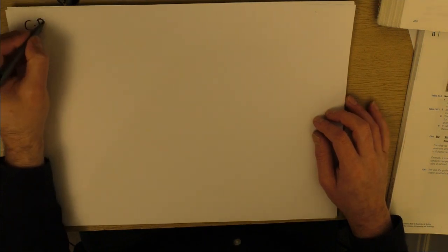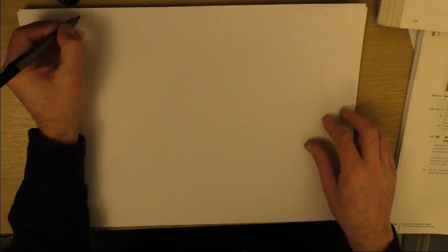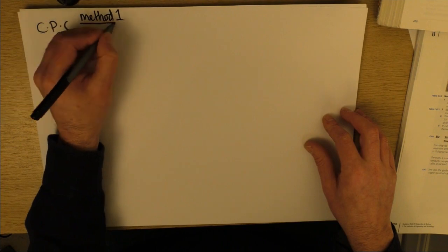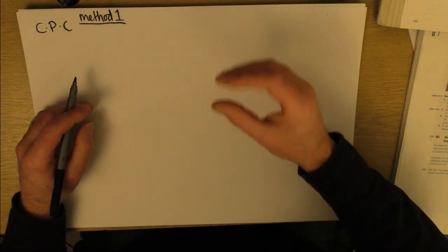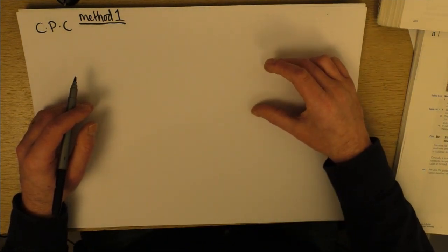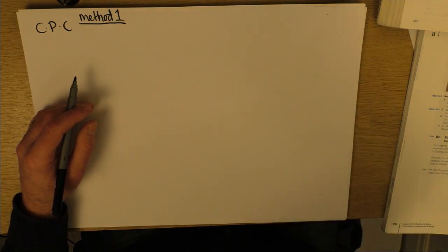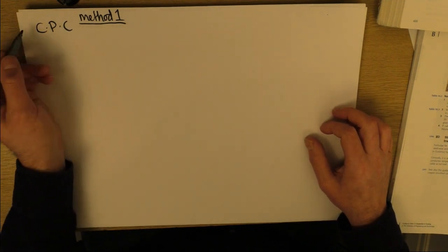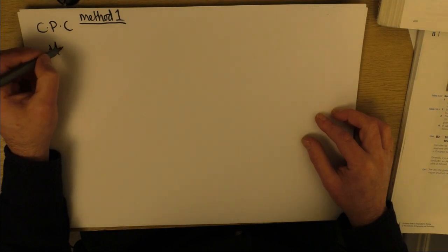Now we need to think about the CPC. So this is method 1. With method 1, we're basically going to choose the CPC and then check for compliance in a couple of ways. Our max Zs, we're going to make sure that we're under that, and we're going to check it for thermal constraints, so what's happening during a fault. So if we're under our max Zs, we need to calculate what our max Zs is.